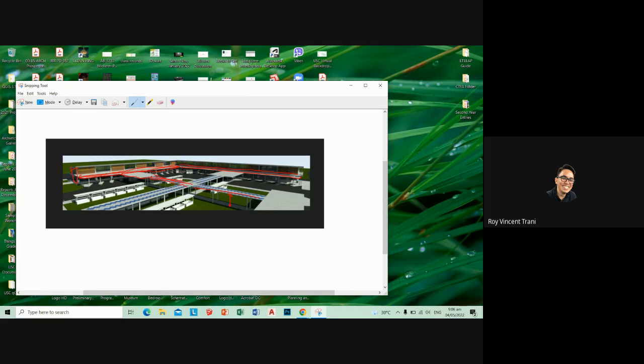Because the problem with making it 4 meters is that if this is a section, this is the ground, this is your person. If this thing is 4 meters up and then it's only that much roof, the person will feel hot. So it's much better to keep it shorter. At least the person is shaded. And I think it will also differentiate it from the main building.